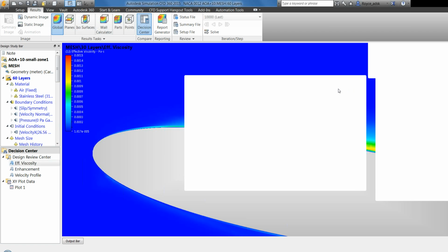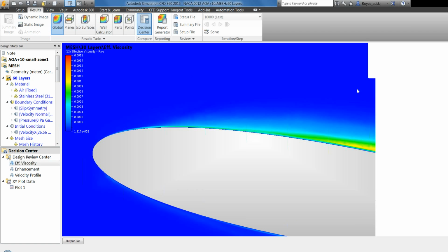Now, if you're starting to look at pressure drops, this is relevant. But what I would actually have you do in that case is leverage probably the 1 or 2 cycles of the mesh adaptation and let that really resolve some of the complex meshing that you would need along the actual shapes of the triangles of your heat exchanger.